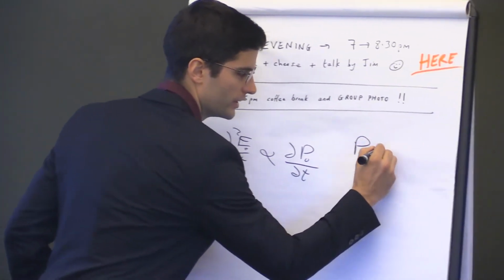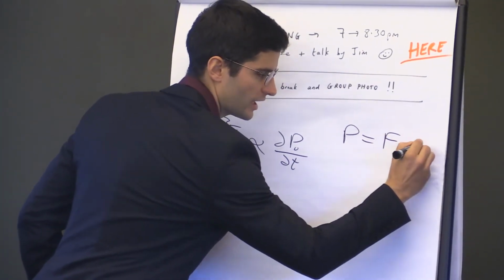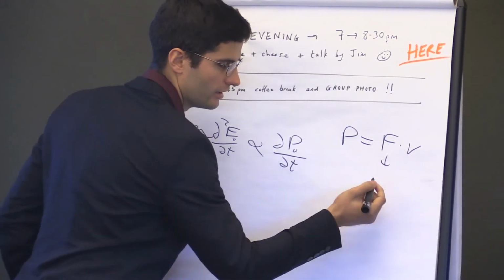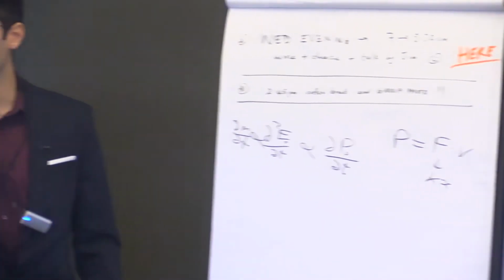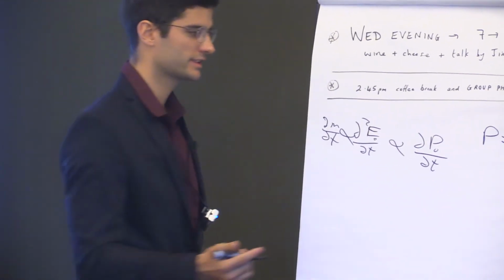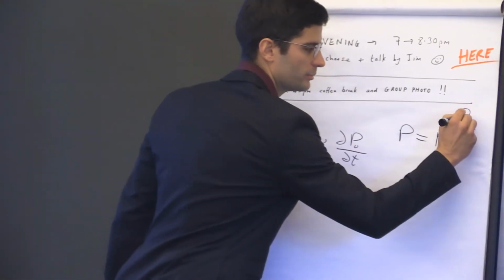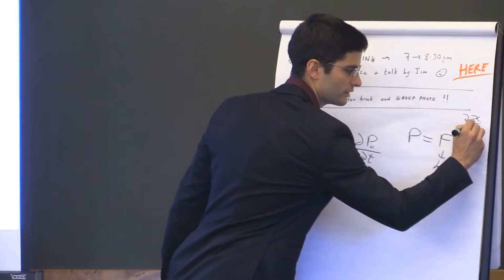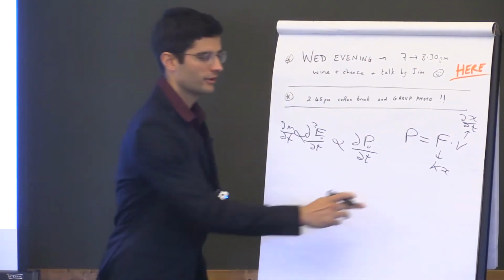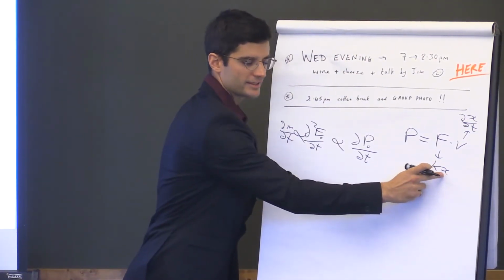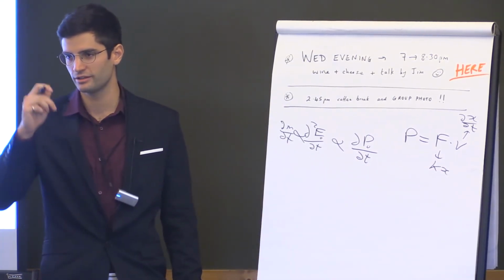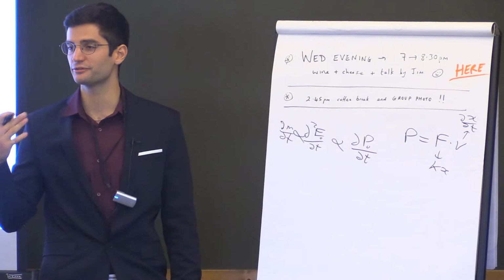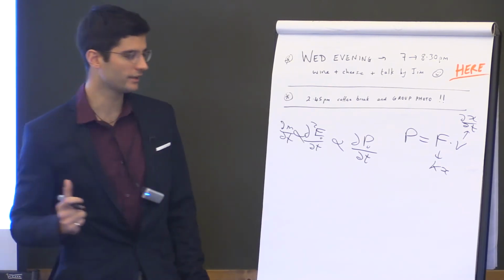The power we know to be force times velocity, and this force could be, for example, the elastic force of the spring or of the actuator itself, and this would only be the first derivative of the amplitude. This is caused by the frequency signal that you're putting in, so it also oscillates at the same frequency as the voltage signal you drive the piezo at.